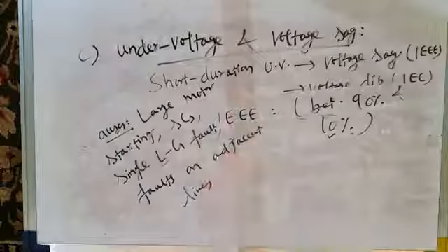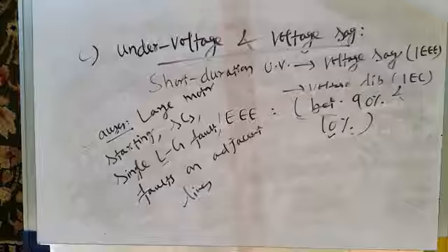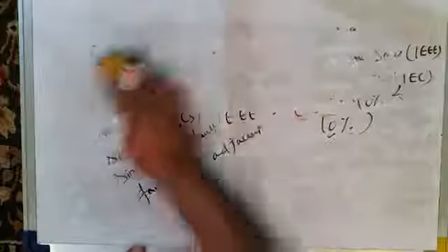So these are various causes of voltage sag or voltage dip. Now these voltage sags, we have already discussed in one of the lectures, are really a cause of concern for all industrial processes. These voltage sags result in tripping of the computers. They affect sensitive loads like hospitals. They result in maloperation of critical, sensitive equipment, like in the operation theaters, where various equipments may maloperate.